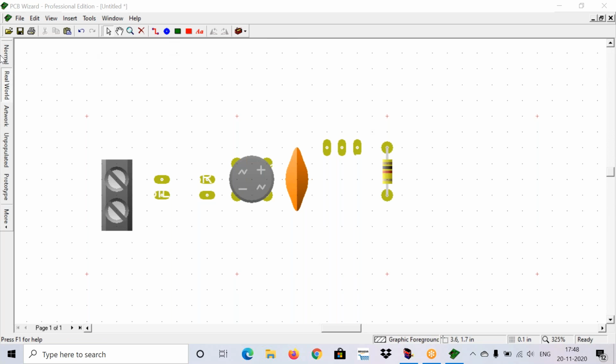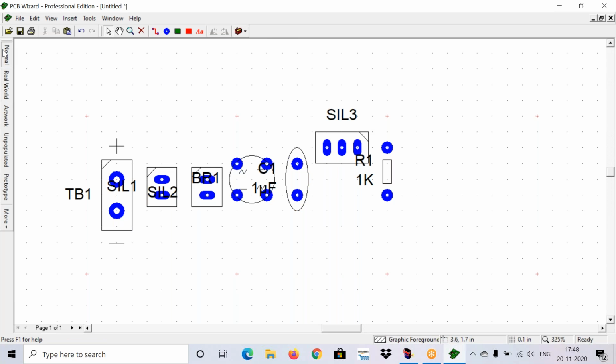Now the next circuit is a simple fire alarm, right? I will design the simple fire alarm circuit layout and then we will close it for today. Tomorrow we will design the circuits related to ICs, because while designing the PCB layouts of ICs, you may get confused easily, you may not identify the pins correctly and you may give wrong connections. While routing there should not be any short circuits, because one track should not overlap with another track and one component footprint should not overlap with another footprint.